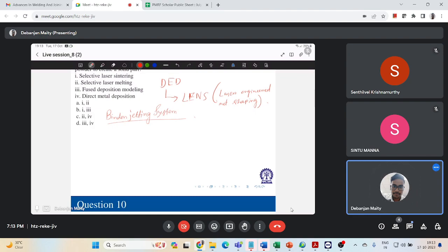If you think of a binder jetting system, this technology has provided a lower cost printing system, which is capable of producing complex geometries out of various metals and ceramics. Now, the working principle of a binder jetting system is similar to powder bed fusion, in that the printer head selectively deposits a liquid binder onto the powder bed for each layer. So, in simple terms, we can think of it like that.